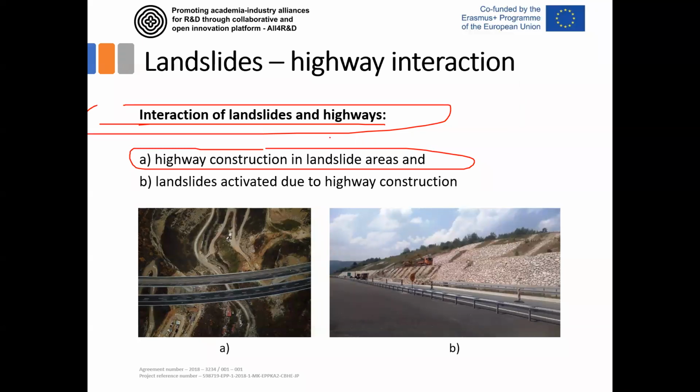The main indication regarding the answer to the question of whether a landslide is a problem or not is the depth of the landslide. What does it mean? If this is the soil-like material and this is rock material that is not prone to sliding, very good stiff material, the main information about the landslide is this. And this is the depth, the height of this soil-like material that is prone to sliding. So some failure surface would look like this. So this is moving soil mass that is unstable in natural conditions.